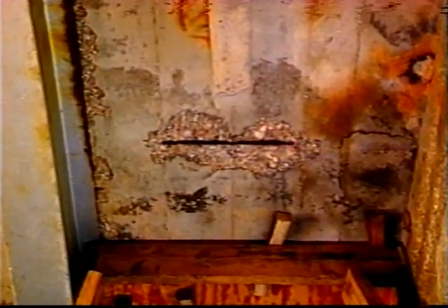Concrete members can show a variety of problems. Scaling is the continuing gradual loss of surface mortar and aggregate over an area. Spalling is the loss of a concrete surface thickness over an area. Such deterioration can be caused by deficient materials or construction, by unexpectedly severe environment, or by reinforcing steel corrosion.